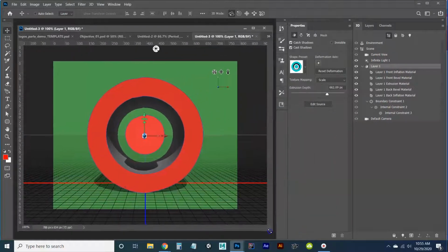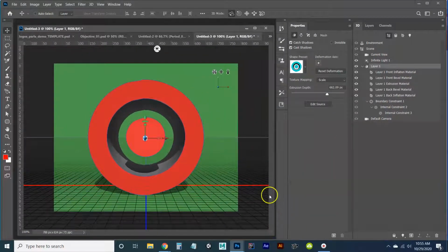And now I want to make sure you organize your user interface to make this as easy as possible for you. So the 2 main windows that we're going to use when we play with 3D objects in Photoshop are the new 3D layer, which has a bunch of layers. We'll call these layers in them. And we also want to make sure we can see our properties window very easily. If you can't see that, or if it's embedded somewhere else, make sure you detach it, pull it out, and you have it readily available.